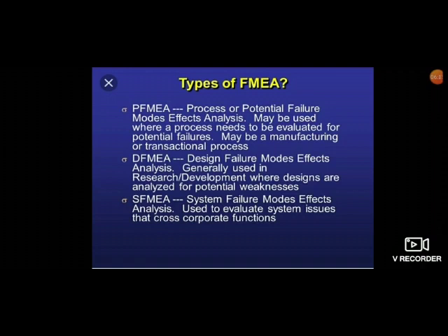The third one, process failure mode and effect analysis, is a methodical approach used for identifying risk on process changes. It initially identifies process functions, failure modes, and their effects on the processes. If there are design inputs or special characteristics, the effect on the end user is also included.